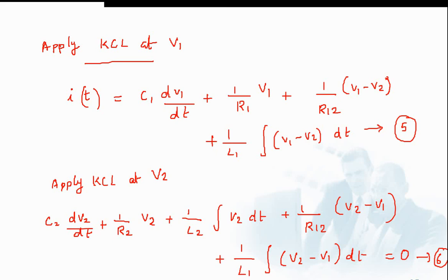In the force current analogous circuit, your output is voltages V1 and V2 and the input is current I. So by applying the Laplace transform, you can find the transfer function. Note that this applies for the force voltage analogous circuit and for the mechanical system also.